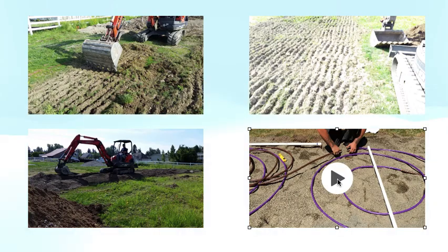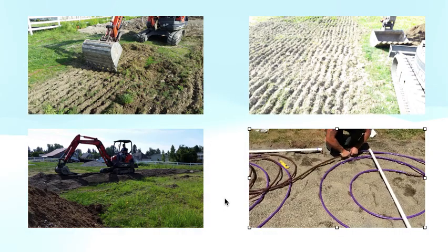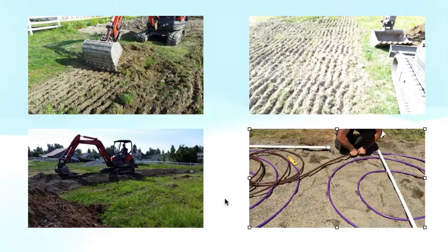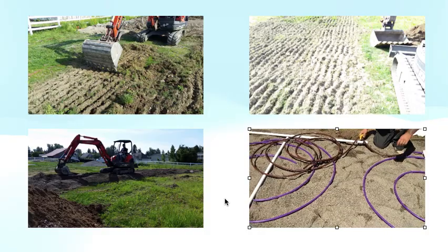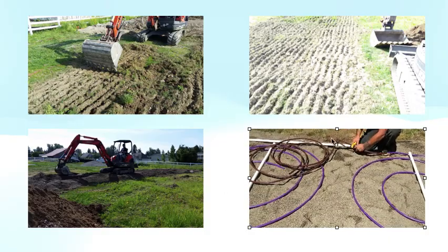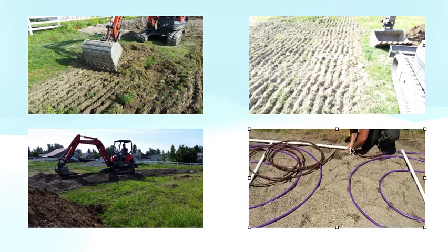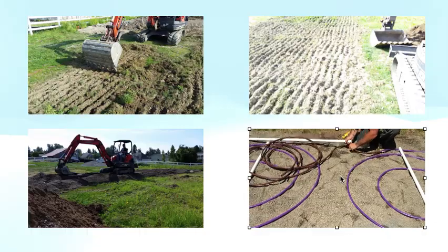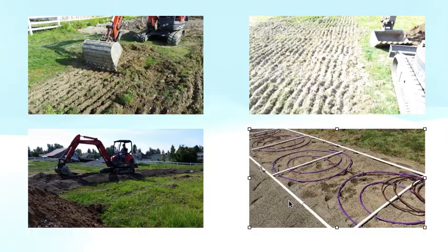And so you'll see here the last thing we'll do is attach these coils. As he's making these connections, he's got the coil, and he's got this brown tech line, which is something that LOWRIDGE provides, and he's making the connection here. If you can see right below his hands, he's making that connection into a little elbow at the end of this line that has a barb fitting that will attach drip tubing together.